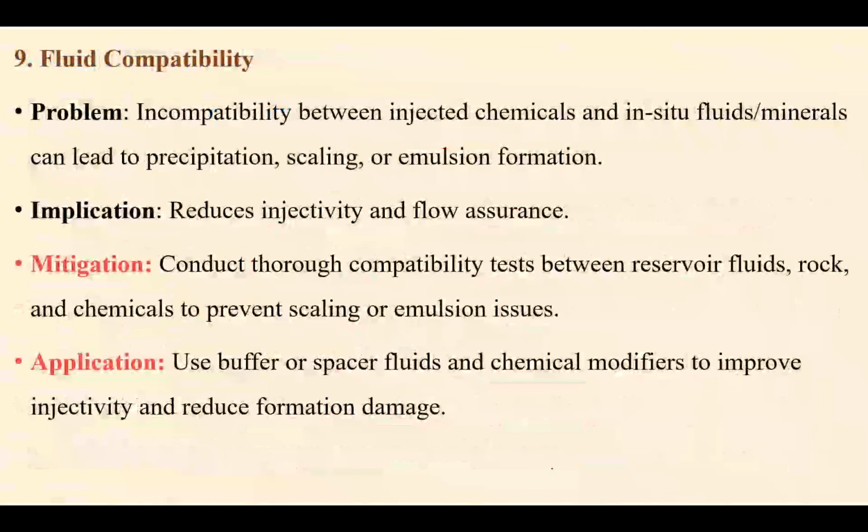Then the fluid compatibility. As I already mentioned, whatever chemicals you are injecting should not react adversely with the reservoir fluids, and there should not be uncontrolled adsorption, that is loss. So for that, proper flushing is very much important, so that after the pre-flush the condition will be much more in favor of chemical injection, and then ultimately it can improve the recovery.